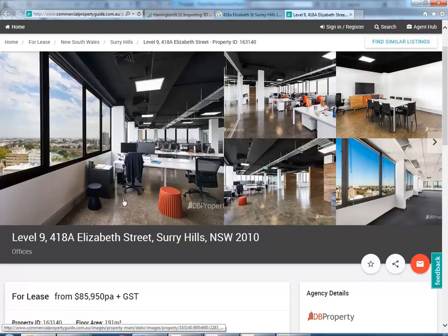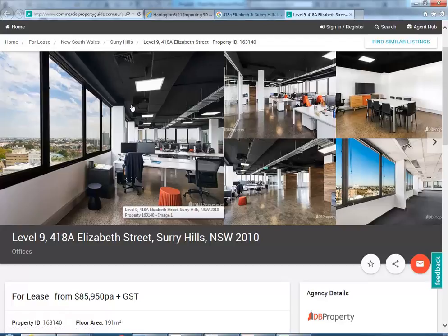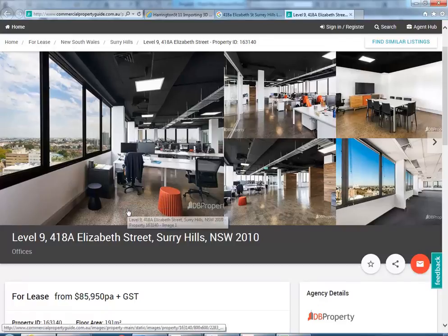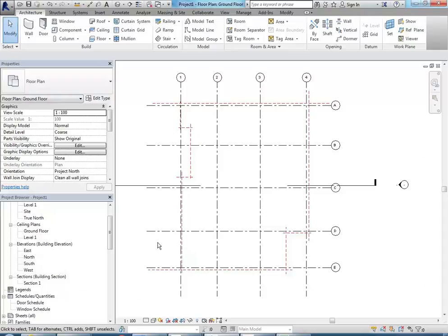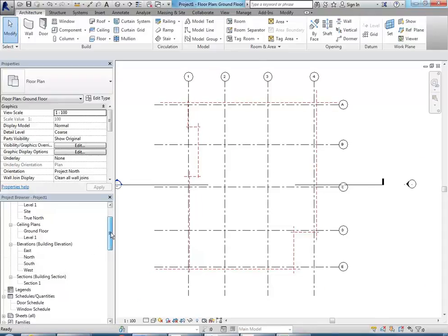We don't really have a lot to do here because we just have a floor level, and then you'll have a ceiling level, but that might be ceiling tiles or it might be the grid level, and you may be removing the tiles the way that they have been here. So that's an option, but either way you want to nominate that level, and then you need to nominate the level of the floor above as well. And that's it. So at the moment there'll be 2 levels, we just need to add 1 more, and I'll show you how to do that.